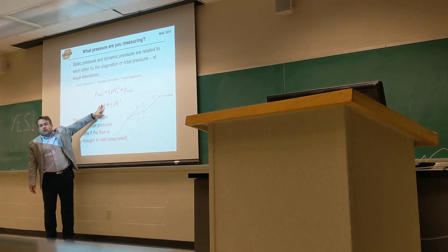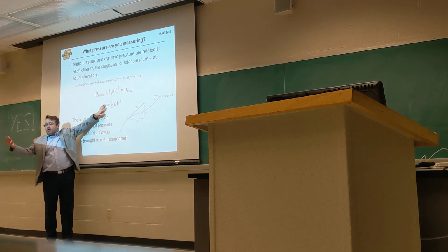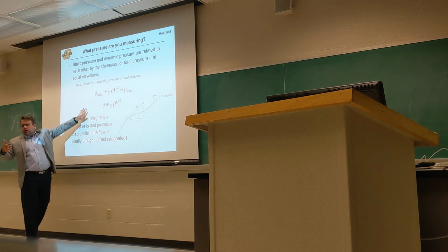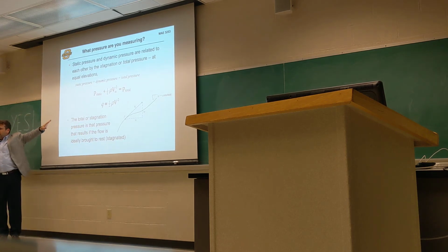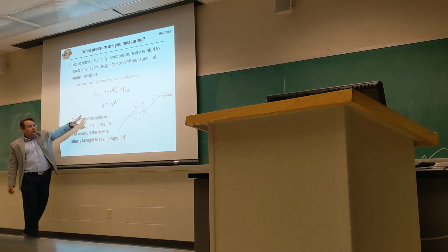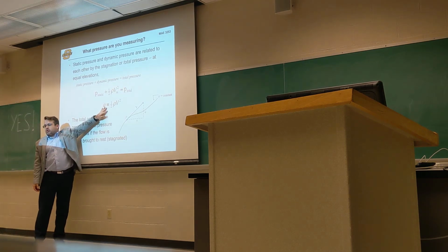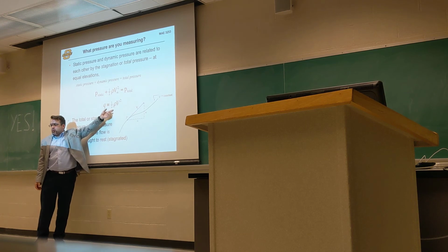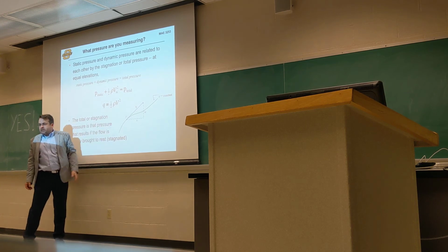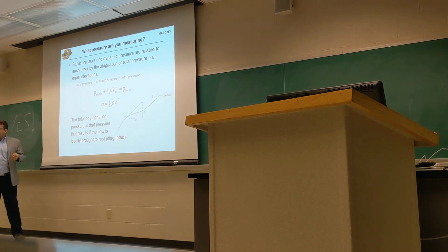But whenever we have a fluid that's moving, we also have the dynamic pressure associated with it. And we call this thing Q. And when we're, say, for example, looking at wind tunnel tests, we don't think about it in terms of velocity. Velocity is not as important as the overall dynamic pressure, because it's these two things that are important, the density and the velocity that you're operating at. What is your value of Q?